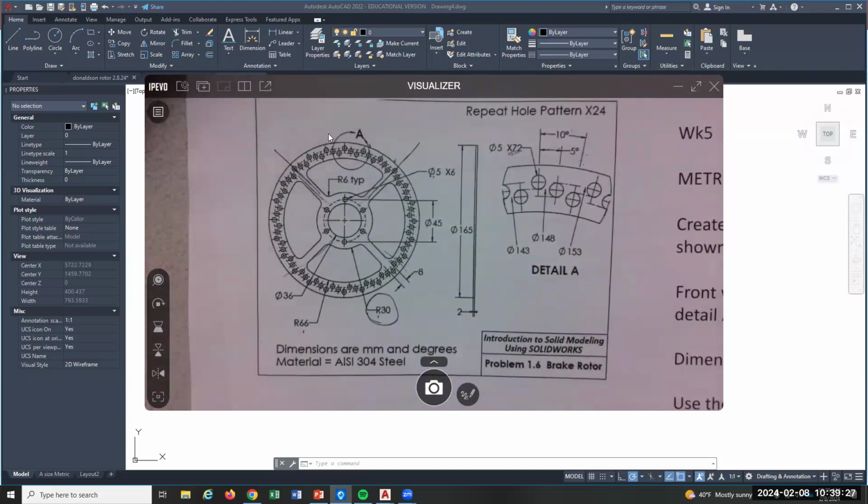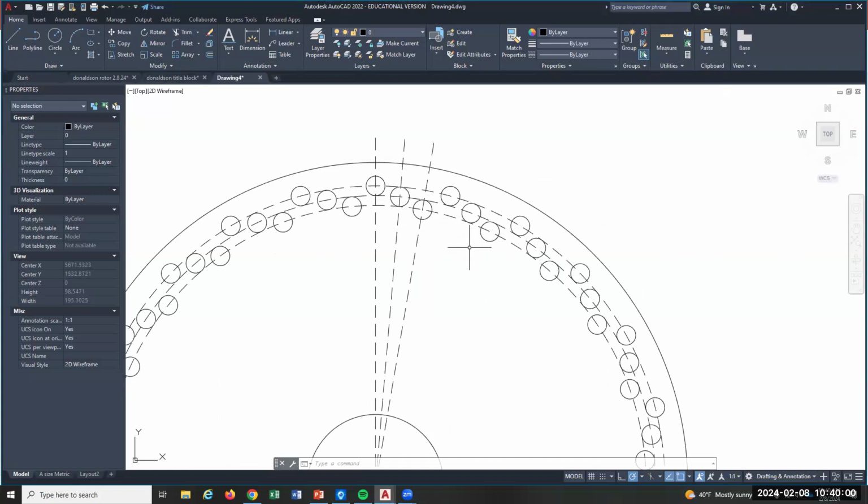What's that weird circle thing at the top of the drawing? Yeah, so that's a blow up. Right? So this is detail A. Notice detail A appears to be bigger than the rotor, right? So this got scaled. It's 2 times bigger, actually. It doesn't say that. It should say 2 to 1, detail A 2 to 1, meaning, hey, we blew up a section so you could see it easier, right? How would I do that? Or if I wanted to do that for my drawing.